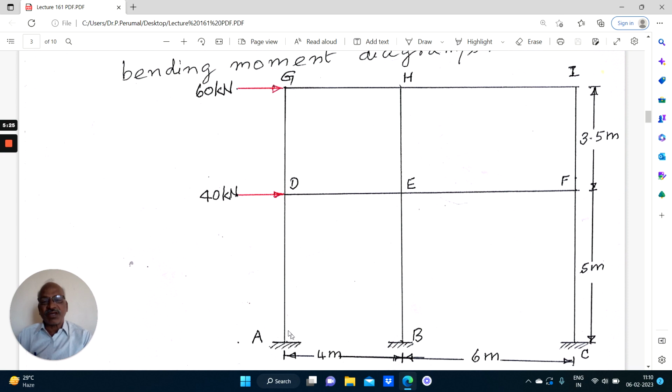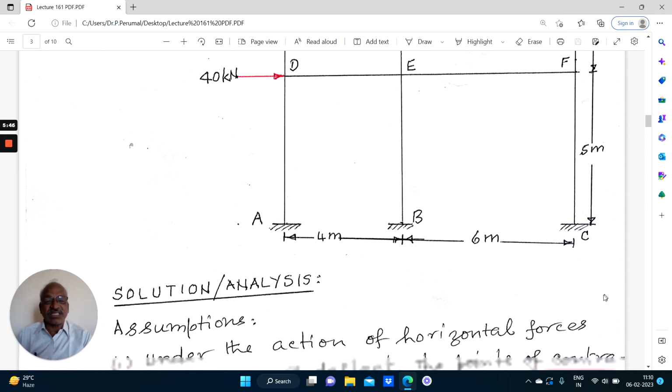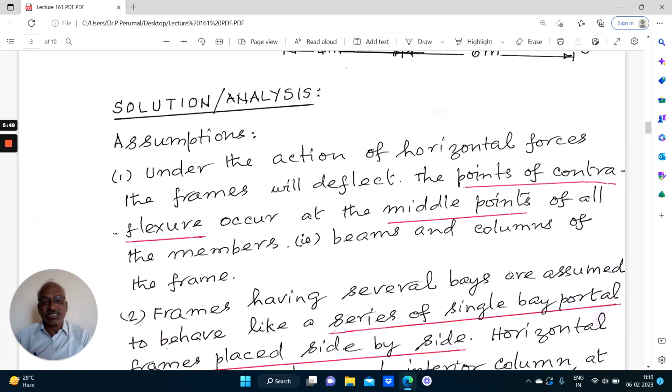And we are going to make one shear equation assumption. So we will find out the shear at the mid heights of columns, at mid heights of the top story columns and the bottom story columns. So these two will be the additional equations which will make the structure statically determinate. Right. And with this introduction, these are the assumptions. Points of contraflexure.